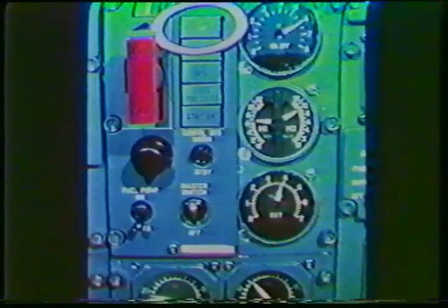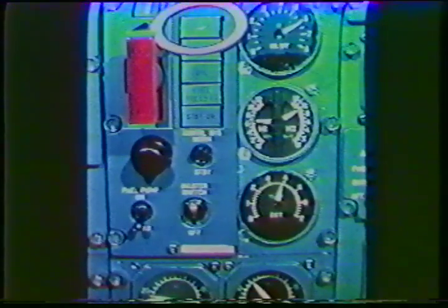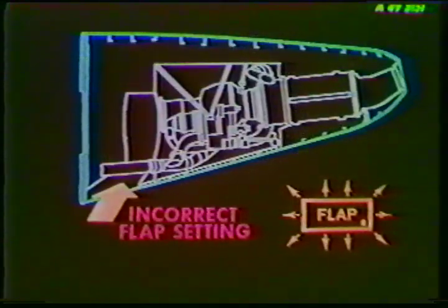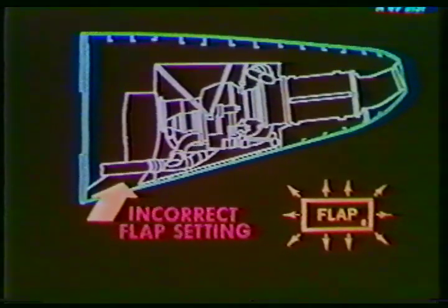Above the fault light is a flap light which will illuminate amber when the intake flap, located in the APU air inlet, is not properly positioned. The air intake flap is fully open when the landing gear is locked down. When the landing gear is no longer down and locked, the red lights illuminate on the landing gear annunciator panels.